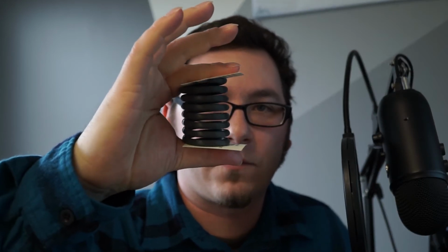So we'll walk through this method that uses an old surfacing trick to create interactive geometry in SOLIDWORKS. We have 2 components that move up and down. All we'll do is simply create a boundary on each one of those components. That boundary will shift with each of the components, and we'll stick a part in between that will move with those boundaries. Now, the sticking point for this technique, usually in the past, was creating a helix that actually updates with those boundaries. And that's where our surfacing trick will come in handy. Let's check it out.